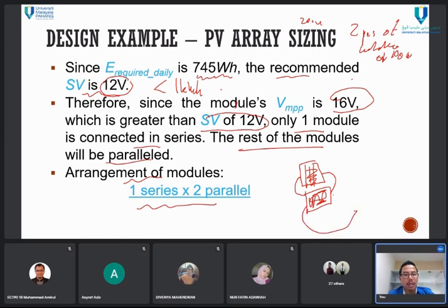And then this is the charge controller, CC. Let's say this is minus and this is positive. Then we have the battery here. Sorry, everything is abbreviated. Battery. It means that our modules will be connected in parallel. Like I told you, we have the connector. You can buy this connector. It is called the MC4 connector. I'm teaching you this one. You can buy it online. MC4 connector.